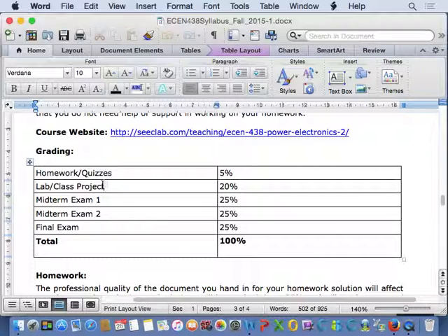So the type of UPS you choose will depend on the type of load. Again, it's a power conversion device, and its design and choice will depend on the type of load. At the end of the day, what is it doing? It's taking battery energy, which is DC, converting it to AC. All these types of UPSs will be the same thing. And then they're taking mains power to charge the battery when mains power is available, right? So the function of the power conversion from AC to DC to charge the battery, and then from DC to AC to feed the load, is the same.